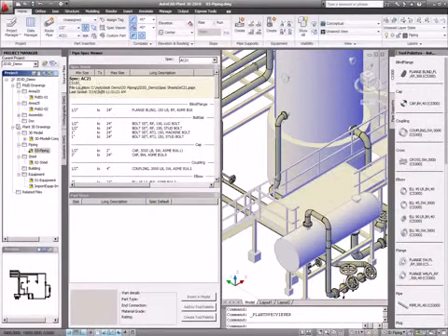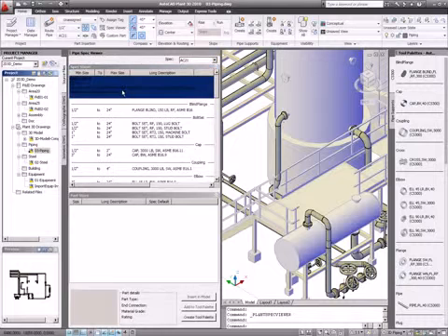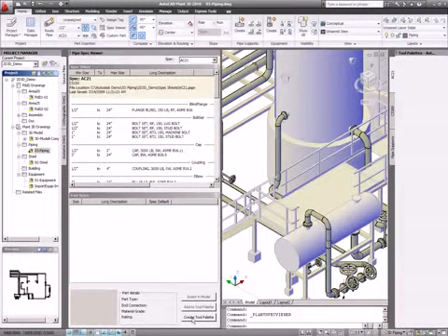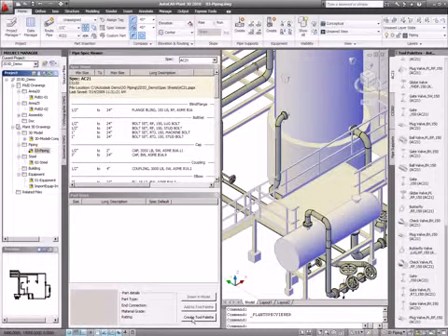As you see here, these are my specs, listing all the specs we have in the project. I select the AC21, select the header file, and then easily create a tool palette. As you see, it automatically brings all the components from the spec into the tool palette. So if we also add some component into the spec, we will also see this component appear in the tool palette.